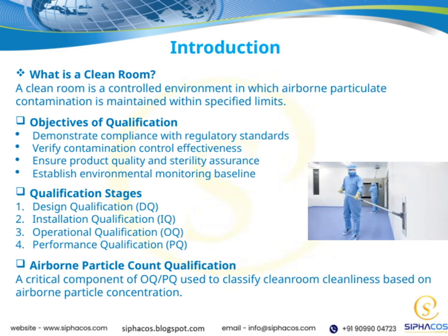Moving on to the objectives of qualification, the main goal is to demonstrate compliance with regulatory standards, showing that our clean room meets all necessary requirements. We also want to verify how effective our contamination control measures are, ensuring they work as intended. Additionally, maintaining product quality and sterility assurance is central, as these are often critical in industries like pharmaceuticals and biotech. Lastly, establishing a baseline for environmental monitoring helps us track and maintain cleanliness over time.